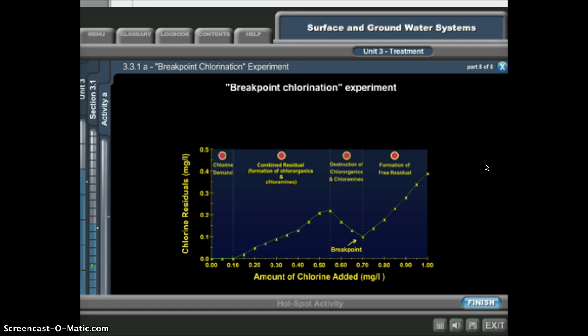Using chloramine as the disinfecting agent results in little trihalomethane production, but it can cause taste and odor problems since chloramines typically give a swimming pool odor to water.